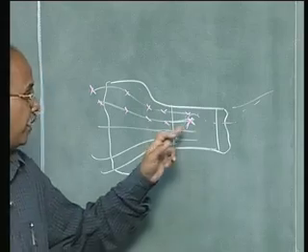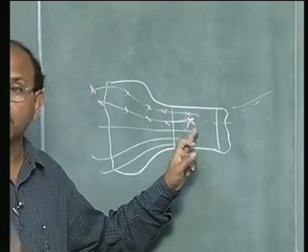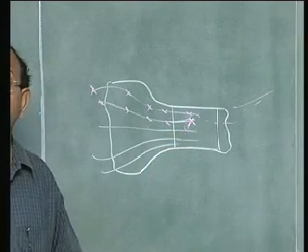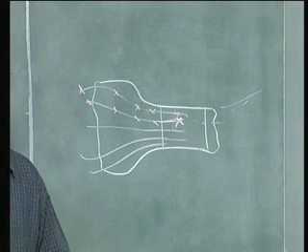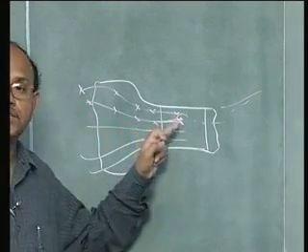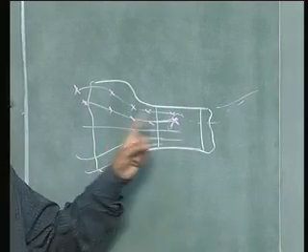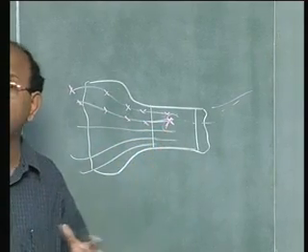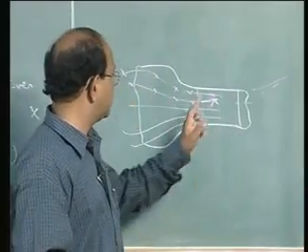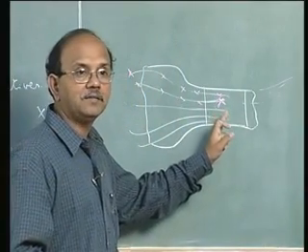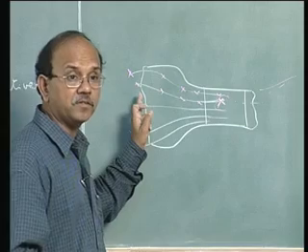But at this point here, for you watching only that point, your velocity may or may not change with time. So from one perspective, the velocity changes with time. From another perspective, the velocity need not or may not change with time. So that is the difference between the spatial and the material derivatives.